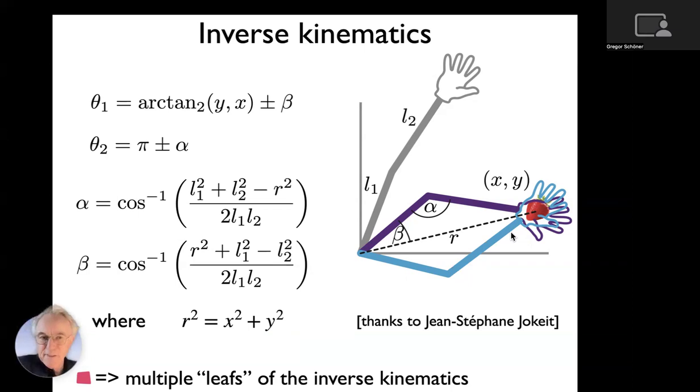You immediately intuit that this is not something you would do as a human, because your joints have joint limits, so if you have this configuration, you cannot actually have the configuration where the arm flips the other way, right? And maybe that's why we have these joint limits, one could speculate. So in robotics, this is actually an issue. So even a robot arm that is not redundant, that has exactly as many joint angles as parameters in the task space it wants to control, still has to select among these solutions.